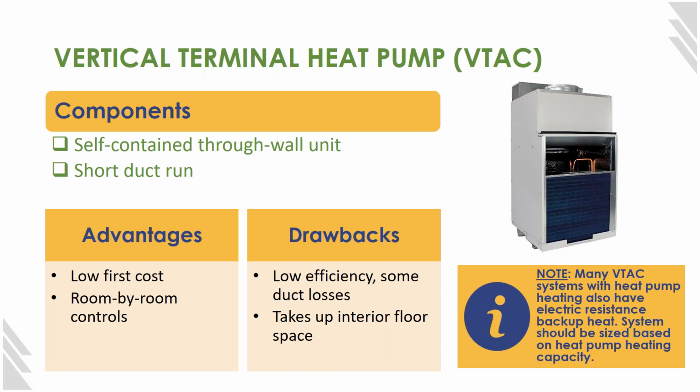The heat pump may have 20,000 BTUs of heating capacity, and then they've got an electric resistance coil with another 20,000. Well, if 20,000 is not enough to meet the heat demand for the apartment, then they should specify a larger heat pump so you can meet the heating demand of the apartment with the heat pump and not have to kick into electric resistance mode because you lose all that efficiency from the heat pump itself.